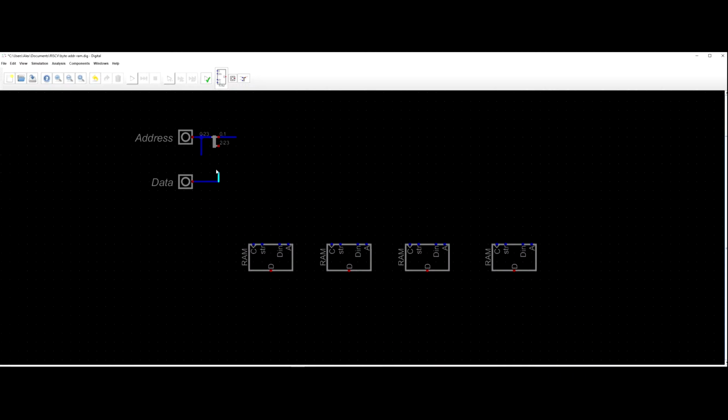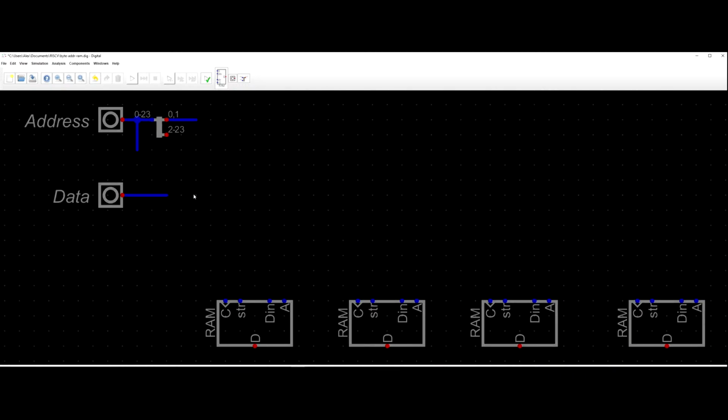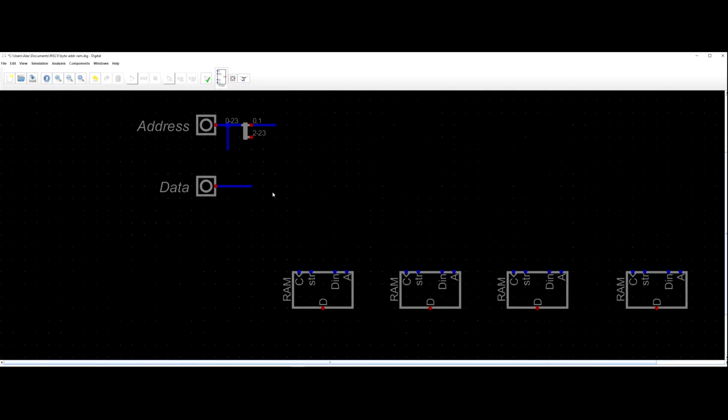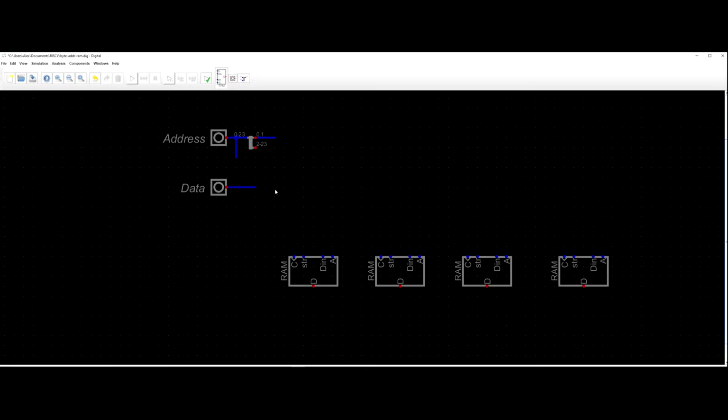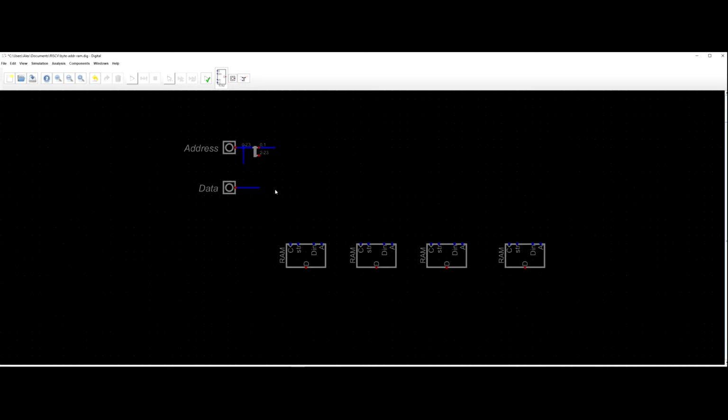If I have 32-bit data, I'm expecting the CPU, if it wants to write a byte, that byte is going to be given to me in the low 8 bits of this 32-bit value. If I'm getting a half, it's going to be the low 16 bits, and if I'm getting a word, it's going to be all 32 bits. And that's the assumption that's going to be made here at this data input.